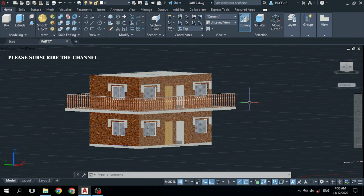I will set that 3D stairs in this side. So I would like to start my 3D stairs from this side, but I can draw the stairs anywhere. Then I will sit in this side. You know that the height of this wall is 10 feet, and the thickness of this slab is almost 9 inches. So I will consider 10 feet and 9 inch distance for that stairs.